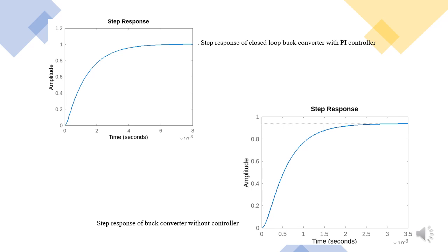In this project, the PID tuner is used to calculate Ki and Kp. Since fast tracking is required, Kp and Ki are equal to 0.471 and 4.9 or 0.49894 respectively. A step response of the closed loop system with the PI controller is also shown in the right figure.